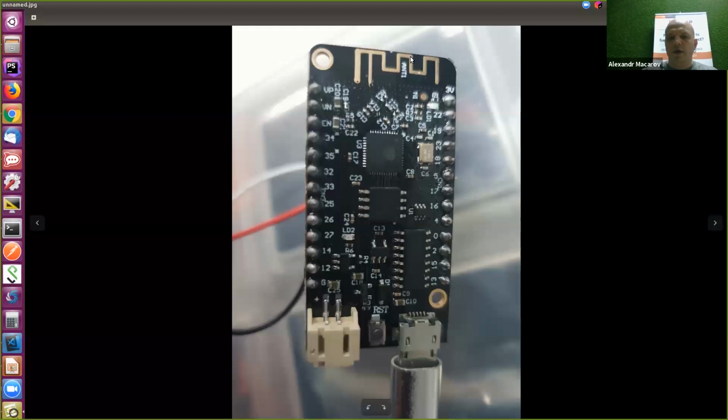This thing on top is the antenna, which is used for Wi-Fi and Bluetooth. This chip here is the flash memory where you store your applications, and it's apart from the main chip. But there are like 4 different modifications of the ESP32 chip, and I think one of them has the flash inside of this chip, so you don't need to use a separate flash component.